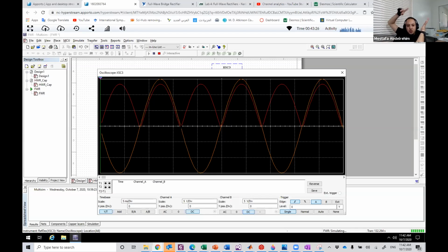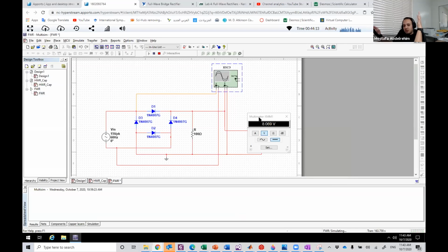Because there are still approximations, and basically this approximation came from that we assume when we do the integration that the output signal is just like the input signal in the positive cycle, but it's not exactly like it. You see guys, there is a difference here. And we also assume that there are no periods in which the diodes are off. That's also a source of the error between the measured DC value and the theoretical DC value. So guys, again, measure V input max, VO max, and VDC, and compare this VDC to 2 Vmax over pi. You have 10 minutes until 11:53.